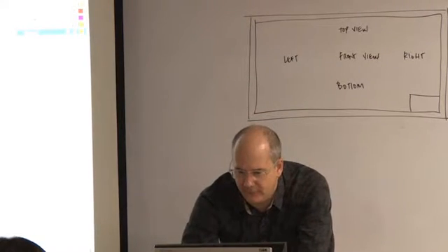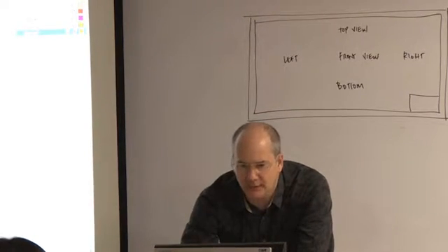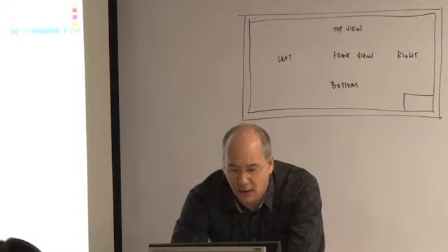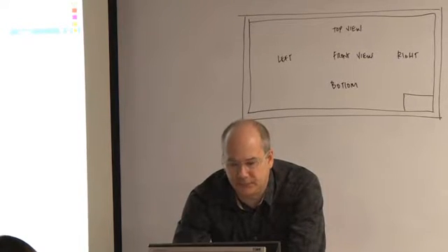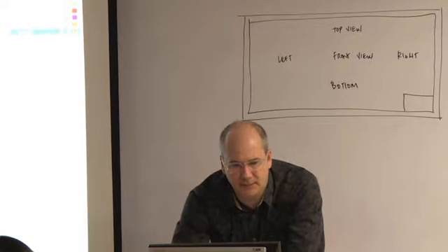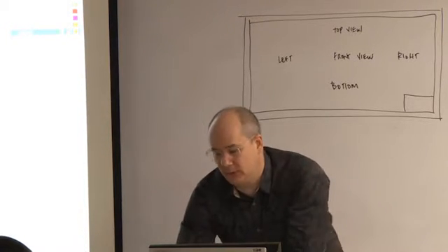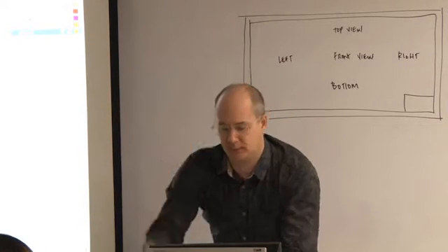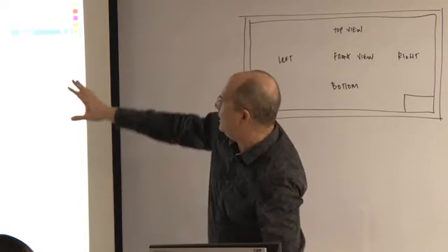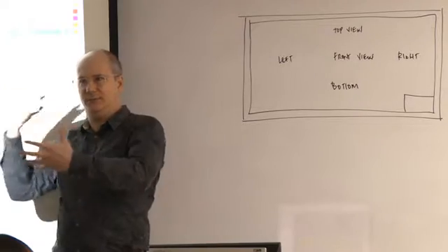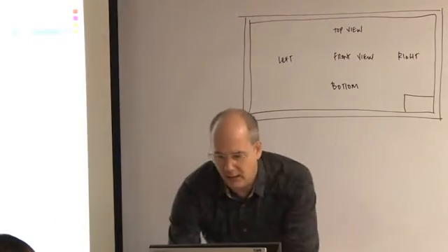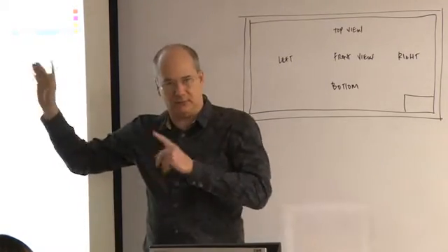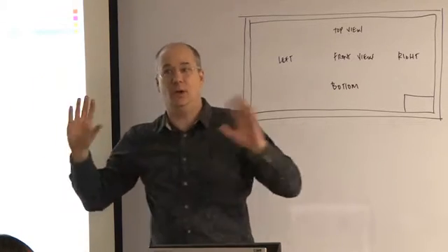First of all, we go up here to Dimension and we zoom down to Make 2D Drawing. Very self-explanatory. We click here, and up comes "select objects to draw." In the perspective view, let's pick the wrong view first to see what I'm trying to explain here. This is kind of the generic view of our design, the view that explains everything. Now a view like this, not so good. It doesn't really explain the design. So I'm going to choose the wrong view to show you first what not to do.